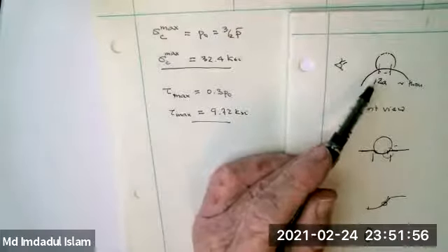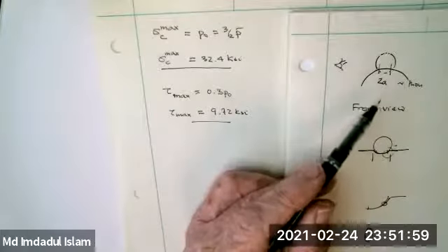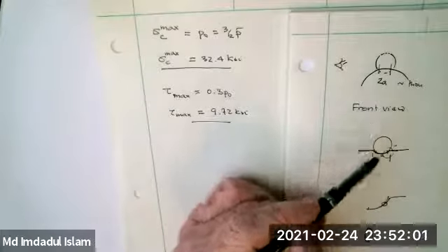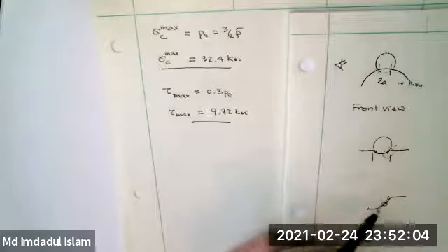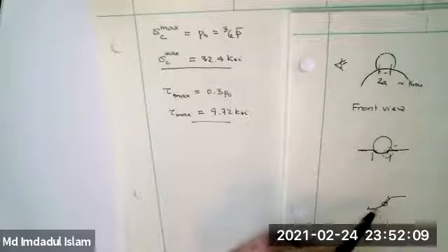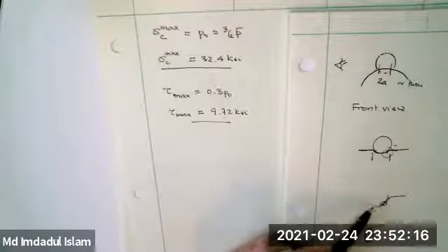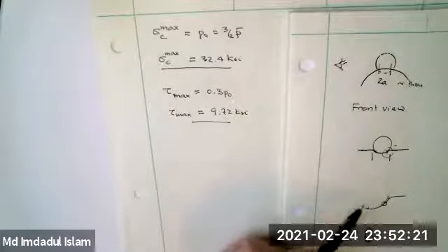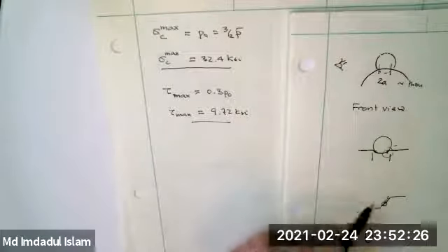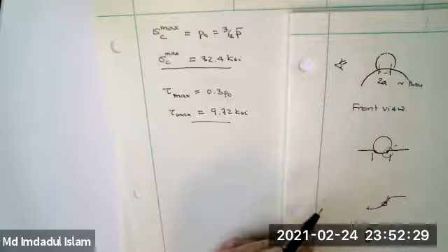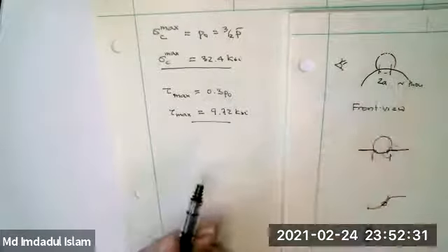This is tricky, okay? The reason I do spherical bearings after roller bearings is the outer plane stuff is a bit tricky, without a doubt. You could get the precise radius of this and try and solve it. I know from practice that they're going to design it so it's about 80% of the width, and so use that. But you could actually go and do spherical contact again here, and get your R as 1 upon R1 minus 1 upon R1 plus, and see what the contact region was. You could actually do that, but I've just done it by measurement here.